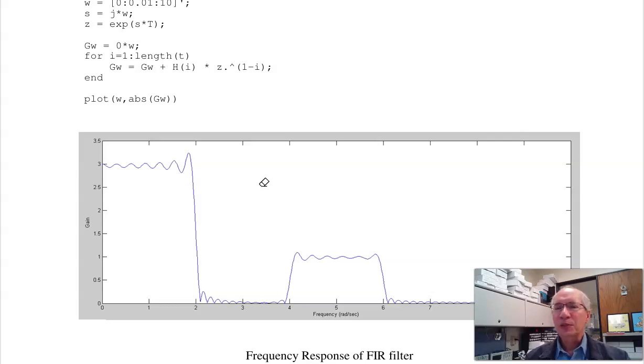So that is homework set number 11 for 376. I can implement filters in the S-plane. That's using op-amp circuits, stuff you do in electronics. I can implement filters in the Z-plane. That's 376 embedded systems. If you want to implement a filter in software, you really should be using the Z-plane. And I can convert from the S-plane to the Z-plane, or I can also do an FIR filter. A couple different options. And that is homework set number 11 for 376 embedded systems.